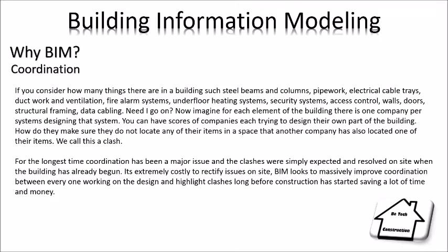For the longest time, coordination has been a major issue, and the clashes were simply expected and resolved on site when the building has already begun. It's extremely costly to rectify issues on site. BIM looks to massively improve coordination between everyone working on the design and highlight clashes long before construction has started, saving a lot of time and money.